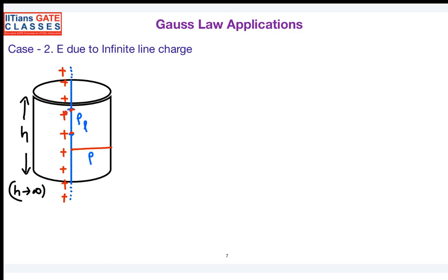First thing is what? Step 1: the line charge should be enclosed with a closed surface. So since the line charge has to be enclosed with a closed surface, I have taken a cylinder something like this. So the cylinder is able to capture the total flux. Is it correct? First of all, can you tell me what will be the flux lines' direction here right now? Since the line charge is something like this, the flux will be radially something like this. Since the flux is generated radially, I have considered a cylinder to capture the total flux.